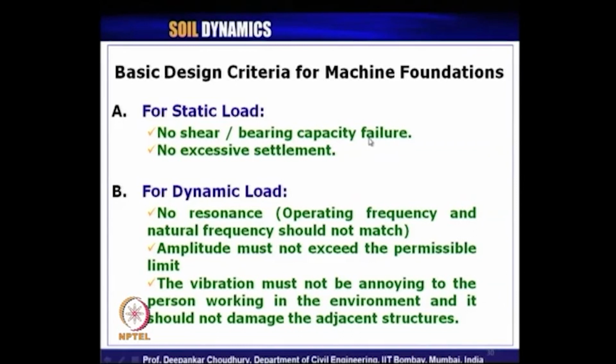That means we have to check the bearing capacity of the foundation and satisfy the factor of safety with respect to bearing capacity, etc., whatever we provide in static design of any kind of shallow footing. Of course, here we are talking about mostly shallow footing. We have to check that criterion.